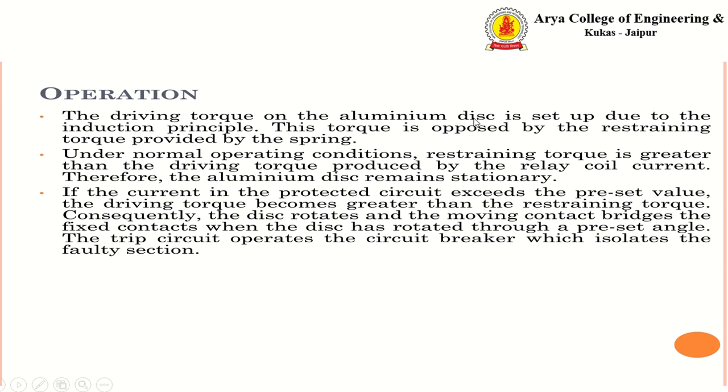The driving torque on the aluminum disc is set up due to the induction principle. This torque is opposed by the restraining torque provided by the spring. Under normal operating conditions, the restraining torque is greater than the driving torque produced by the relay coil current. Therefore, the aluminum disc remains stationary.